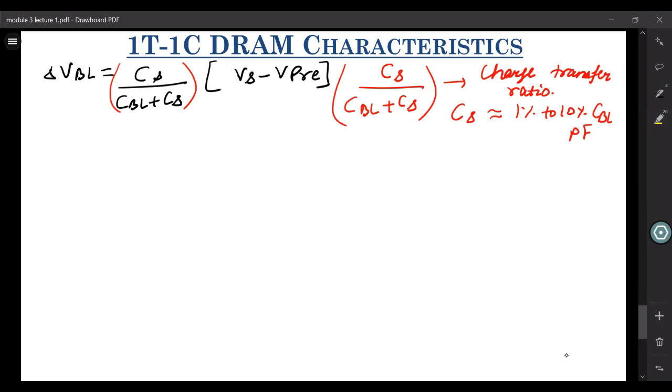The capacitances that you can realize with the elements present in your circuit, like the gate capacitance of your MOSFET, or a MIM cap, or MOM cap, are only in the range of some femtofarads, maybe some 100 femtofarads at the max, which you can realize using monolithic integration techniques. However, CBL is in some picofarads.